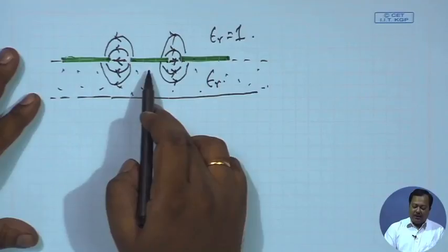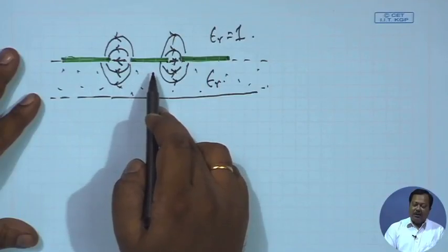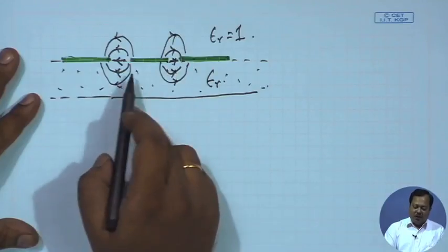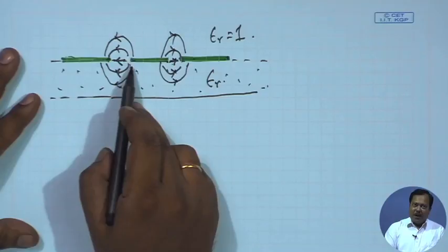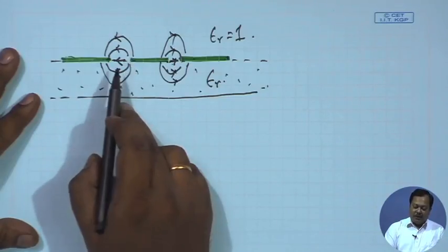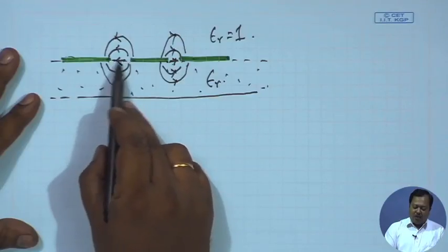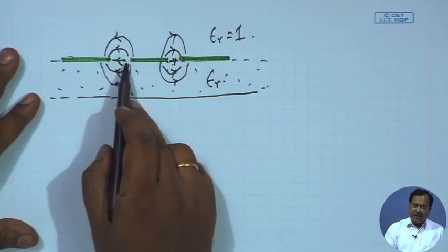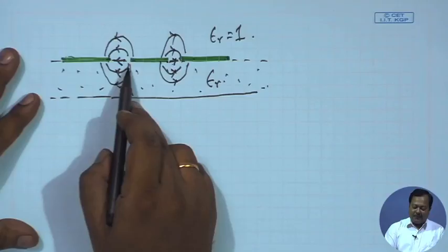And in this case, if I change frequency, again just like the microstrip line, epsilon e will change. We can also control the characteristic impedance. We have some standard closed form expressions. So, if I decrease this slot width, characteristic impedance decreases.